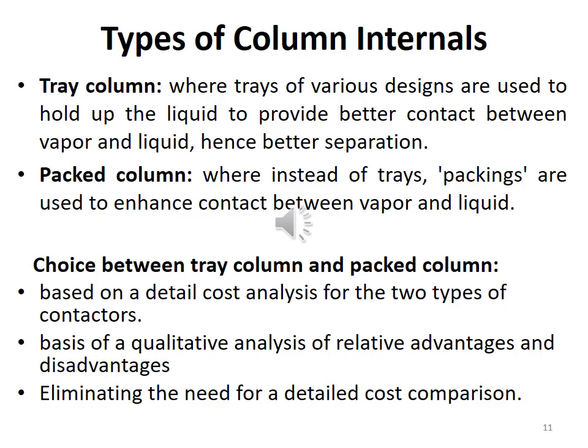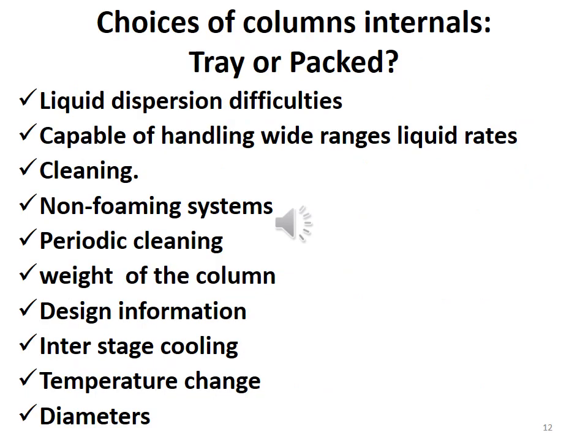Contactor means that which offers a contact place between vapors and liquid, and on the basis of qualitative analysis of relative advantages and disadvantages. So we will choose one of these two types depending upon the cost analysis and the qualitative analysis of relative advantages and disadvantages. These are the parameters which help us to select the column internals, either tray column internals or packed column internals.